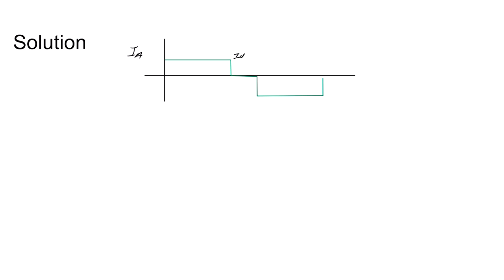Let us have a look at the source current waveform I. So the magnitude of the source current I is IDC for the period 0 to 120 degrees, 0 for 120 degrees to 180 degrees, and again minus IDC from 180 degrees to 300 degrees, and 0 for 300 to 360 degrees.